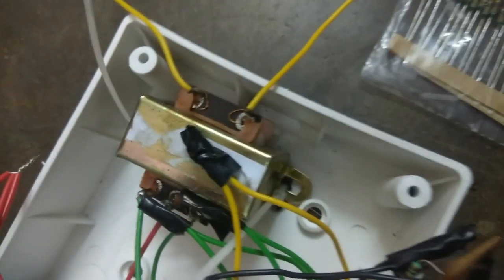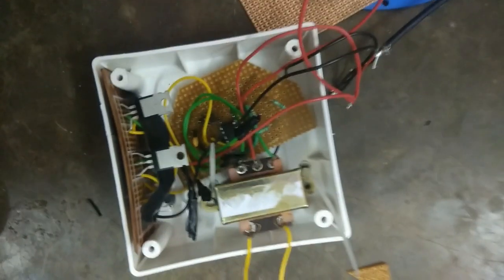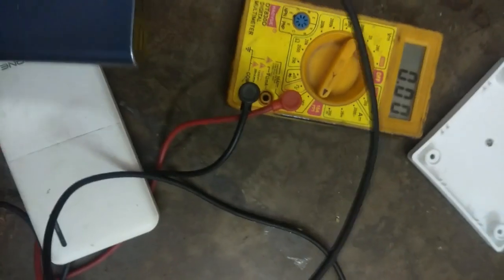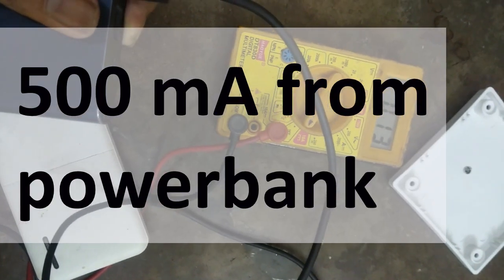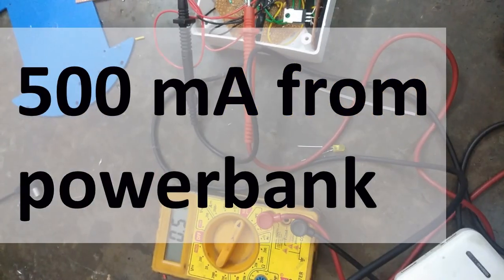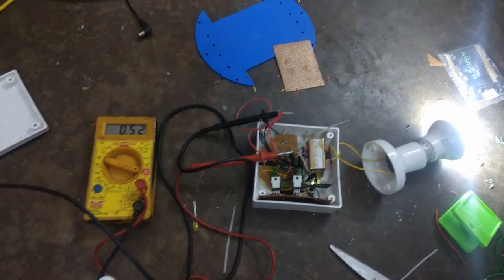After assembly, the whole device looks like this internally. When there is no load, the output from the transformer is 190 to 204 volts, and it draws around 15 milliamps from the power bank without any load. Then I measure the milliamps from the power bank when there is a load, that is this 9 watt LED bulb. So this is the whole circuit. You can see the whole setup design.